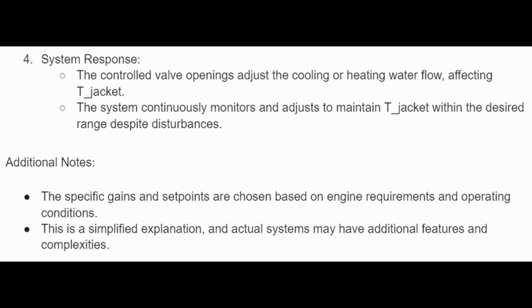The control valve openings adjust the cooling or heating water flow, affecting T jacket. The system continuously monitors and adjusts to maintain T jacket within the desired range despite disturbances. The specific gains and set points are chosen based on engine requirements and operating conditions.